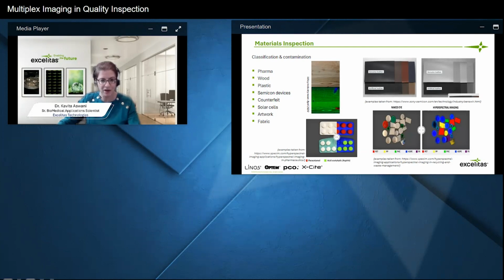For your semiconductor devices, you can inspect PCBs for structural abnormalities or surface defects. And if you use SWIR imaging, or shortwave infrared, you can detect non-surface defects in semiconductors and solar cells because SWIR can see through silicon wafers and chips.